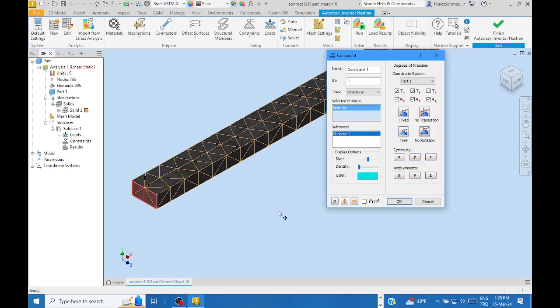But in the basic part of Inventor, there is only one yellowish arrow when we indicate the surface where there is a force, and it may be misleading for the user. Because it is only one vector, it looks as if it is a concentrated force.